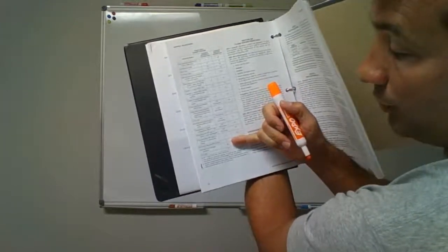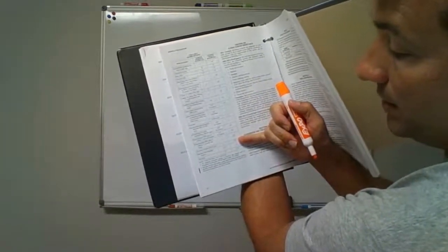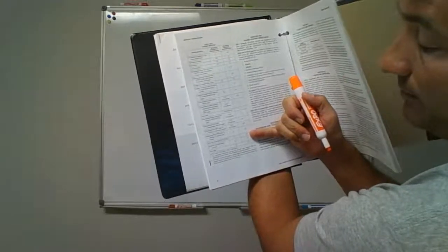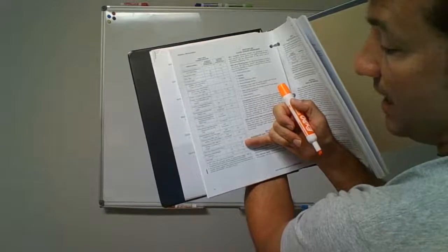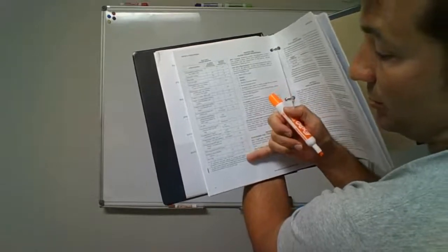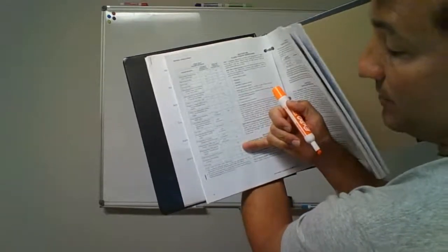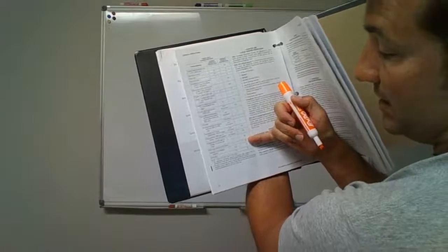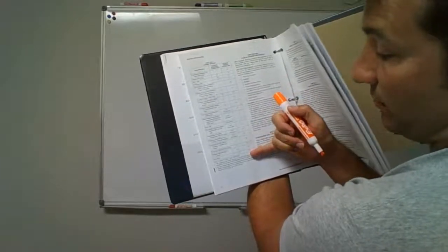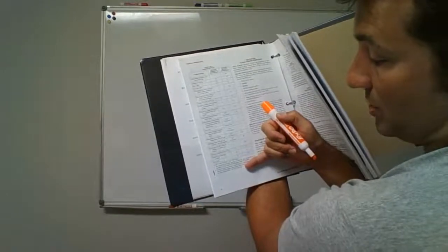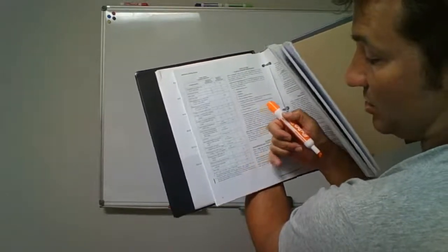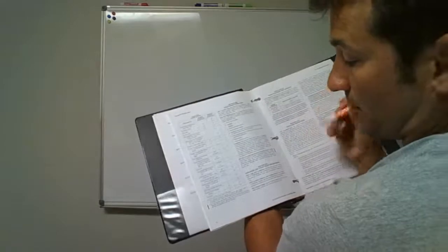If we turn the pipe vertical, we can go a maximum of 10 feet between supports. Look at your little notes. When they have a chart, there's little notes at the bottom. If there's a letter beside the number, which there is in this case, it says a B. It says drop down to the bottom of the chart and read it. For sizes 2 inches and smaller, a guide should be installed midway. Okay.